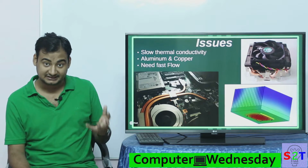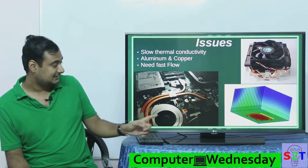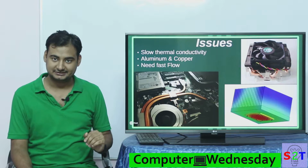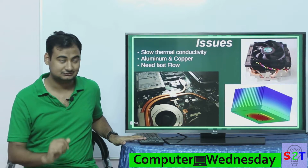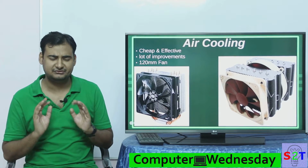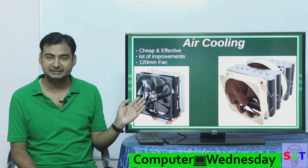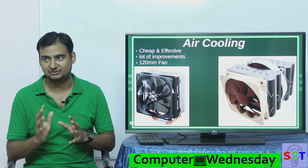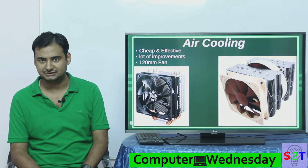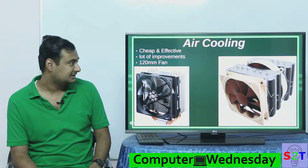And this heat pipe is becoming so efficient that we also use it in your laptop. So your radiator could be here, and the heat pipe is conducting the heat from the CPU and the GPU to your radiator. Now this is how we do air cooling. In air cooling, you have to understand it's very cheap and very effective. I told you, if you have a small heat load, you don't even need fans. Let's say a very small load, like a Pentium 4 or Pentium 3 kind of system with very low thermal requirements, you just put a heat sink, you don't have to worry about anything.